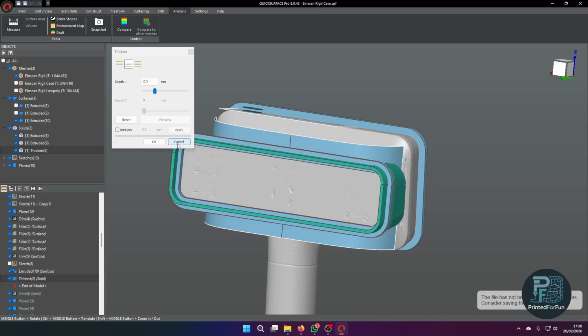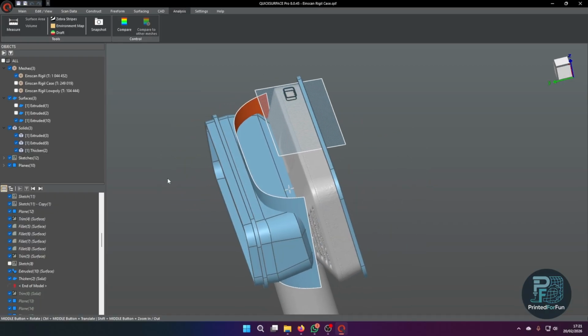It's even more functional than Fusion sometimes. I had the problem a few times of using extreme variable fillets, like multiple variable fillets combined. When I tried to export it and later import it in Fusion, Fusion couldn't resolve these extreme fillets. So maybe stay on the reasonable side, I would call it.